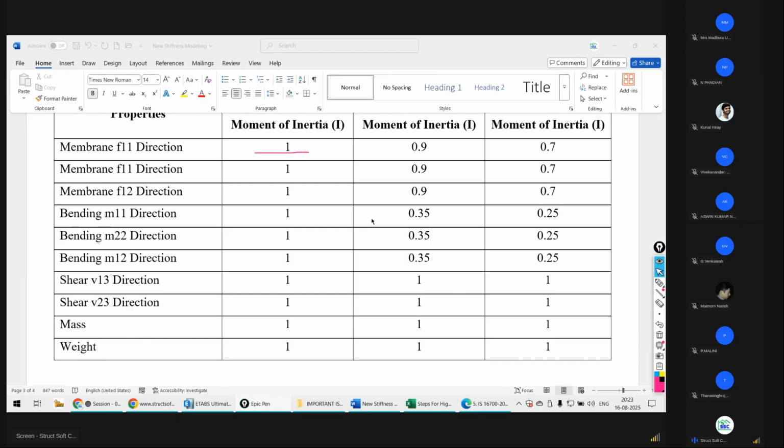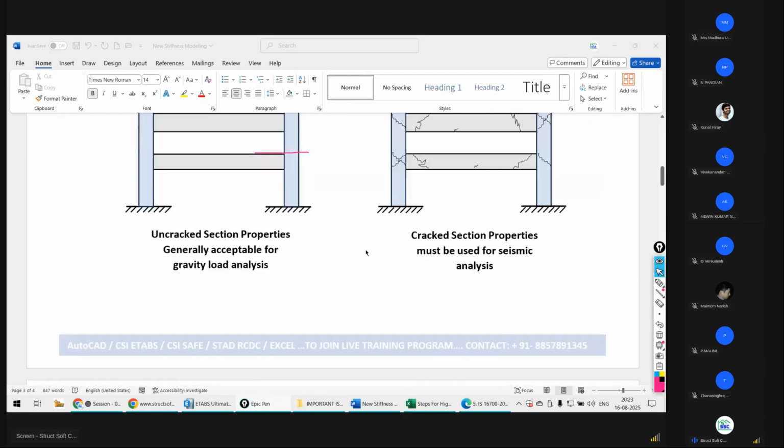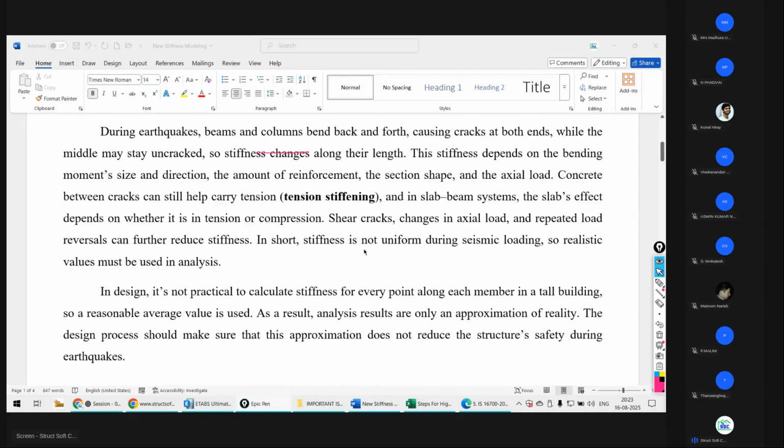But guys, the problem is going to arise when your structure is going to be subjected to seismic loading. जब आपका seismic load आ जाता है and when the heavy wind flow is there across your structure, at that time the problems of the cracking, that is nothing but your flexural cracks, are arising. वहां पर flexural cracks आएंगे. There will be possibility of the flexural cracks and there will be formation of high stress zones during the seismic event, during the heavy wind flow.